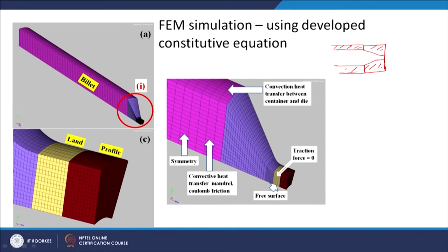So, the billet will be put here, and it will be deformed. The cross sectional area will reduce. So, this is my output which I am going to get, and this is my input. And of course, there will be a ram here to push it through, and the material will come out and there will be deformation, the cross sectional area is reducing and so on.